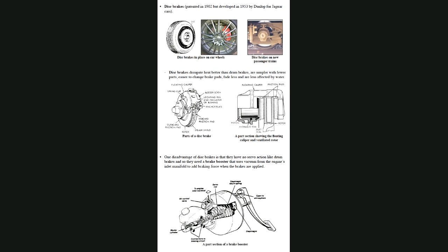You've got a valve here which is connected to your inlet manifold. Now, as you know, when you've got air rushing at a high speed, by Bernoulli's theory, which we'll be doing when we're doing aeronautical engineering, the higher the speed, the lower the pressure. And the lower the pressure, the higher the speed. So if you've got air rushing in your inlet manifold, which you have, to get an air-fuel mixture exploding in the combustion chamber, the air is rushing in at high speed, so therefore you've got a low pressure there.